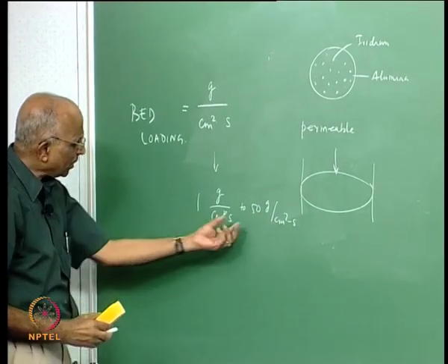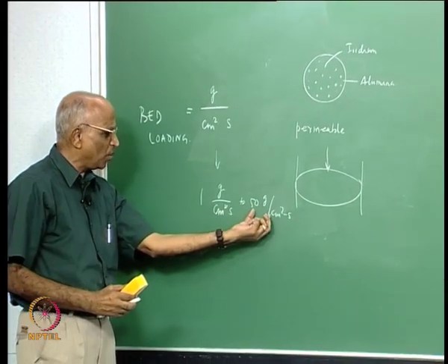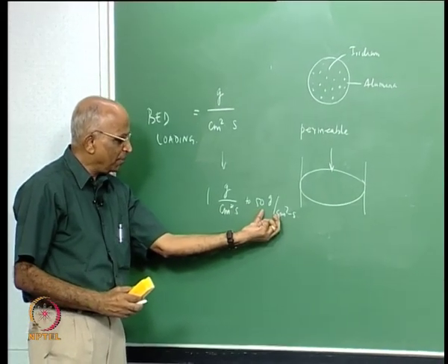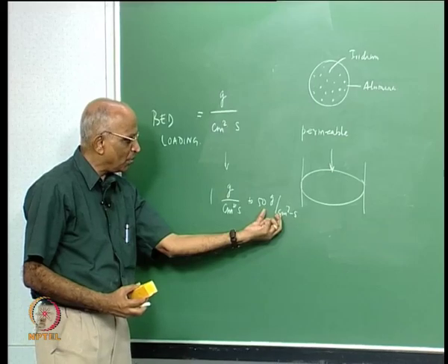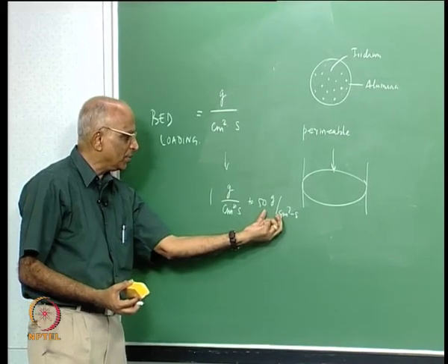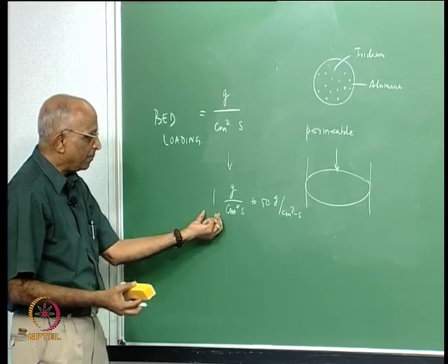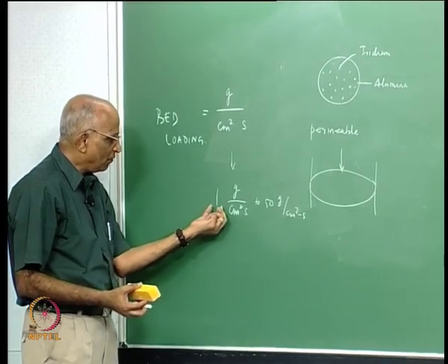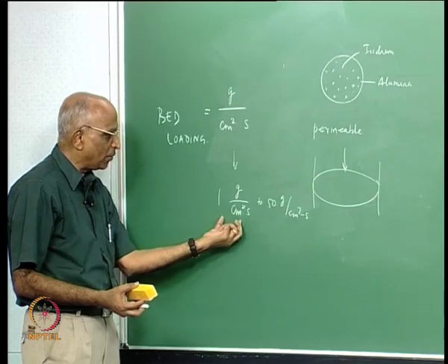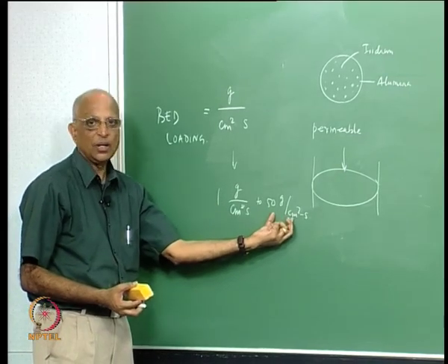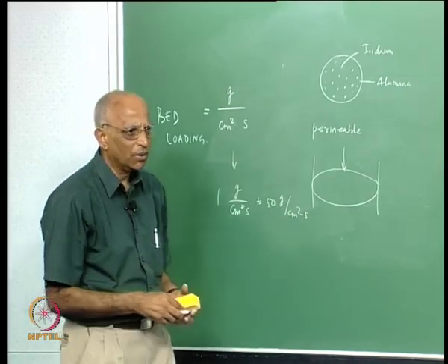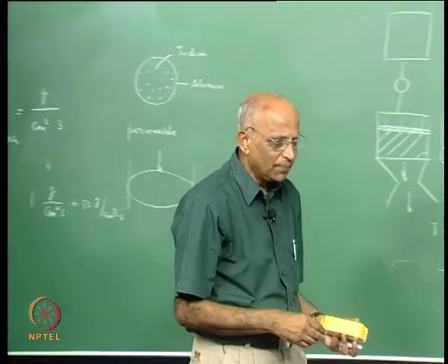For large rockets, whenever we use monopropellant we do not go for high thrust, maybe the maximum thrust we can go is something like 500 Newton to 1000 Newton. The smallest could be anything small, maybe millinewton or something like that. For very small ones we use a small bed loading, for larger ones we use a larger bed loading. This is all about the monopropellant rockets.